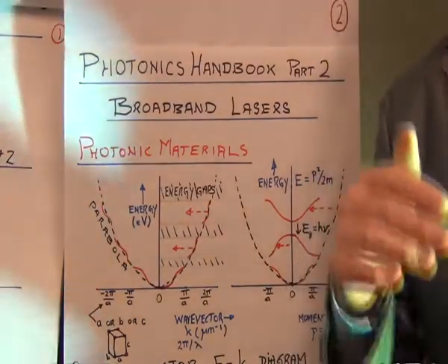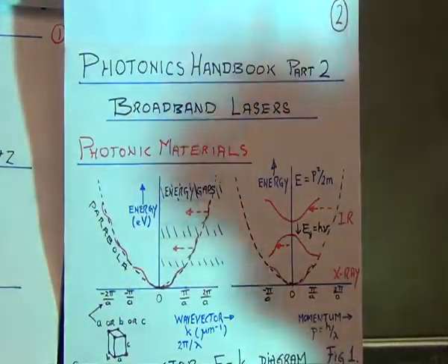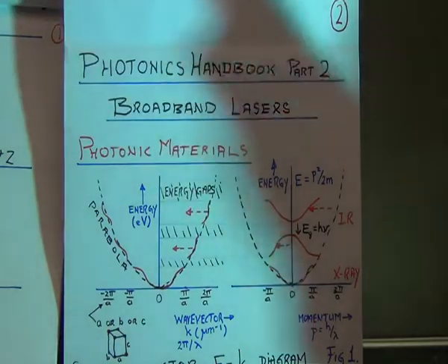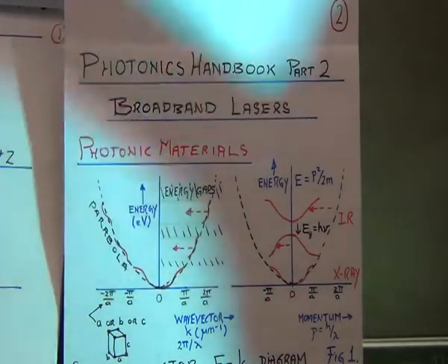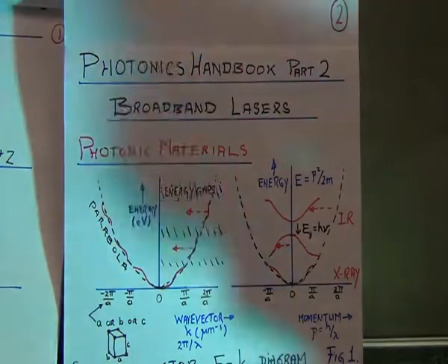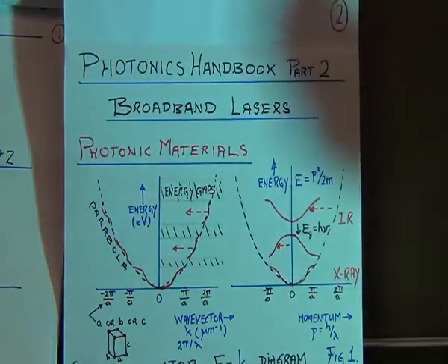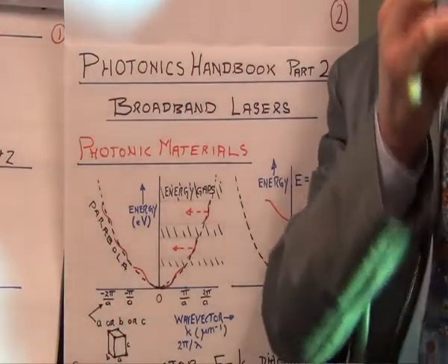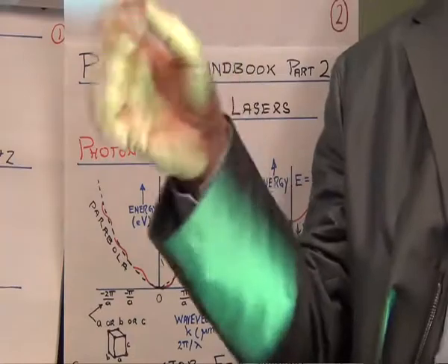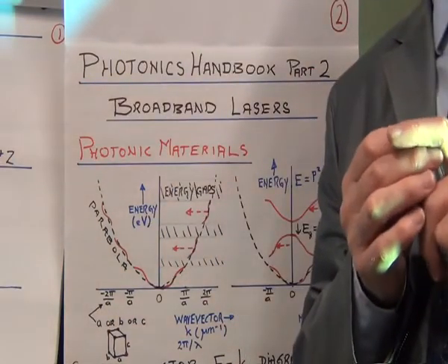That's a tube with a positive and a negative anode and cathode in it. And if a photon goes through there, it ionizes the gas in there and you get a pulse of current. So a photomultiplier tube can pick up single photons. And you put that device up to your silicon diode and you will get an odd blip out of the photomultiplier tube, but very rarely.